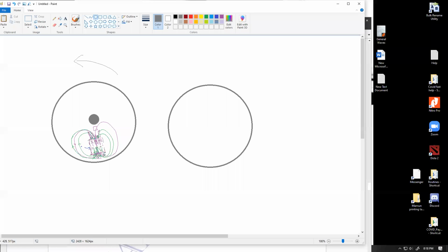I understand, sir. Sorry, you're telling that it can come from all directions, clockwise or anti-clockwise? No. It can come in all directions, essentially meaning that in all the parts where this magnetic field is working, the electrons are being pushed in one direction. All the other parts where the magnetic field is not working, that's where the return path can be. Because in the part where the magnetic field is affecting the metal disk, the electrons cannot move upwards. Within this part, the electrons have to move downwards, which means to fill up that void, electrons have to move upwards in some other places where the magnetic field is not working. This eddy current mechanical braking system is only applicable if you apply multiple different magnets, but not the entire thing under a single magnet.